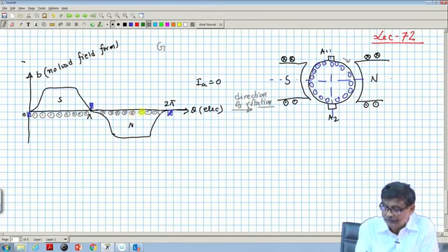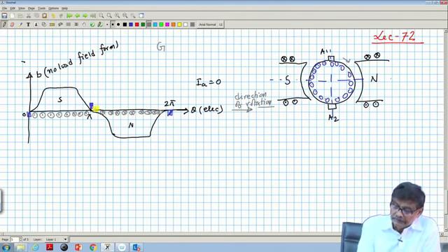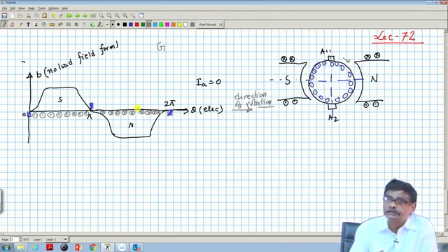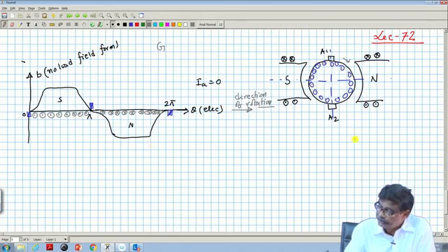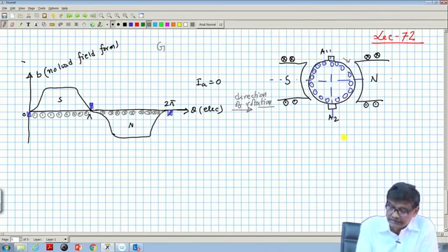So this will be like this. Generated EMF will always be present, but current may or may not be present depending upon whether you have connected a load across the generator or not. Now, let us assume armature current IA is 0, then this will be the only field distribution.